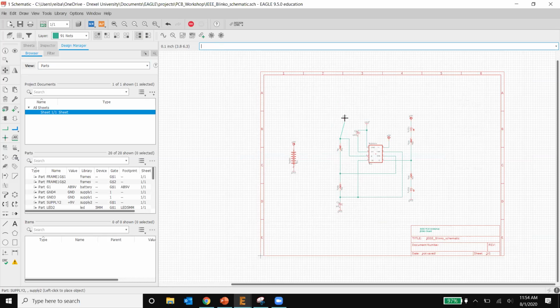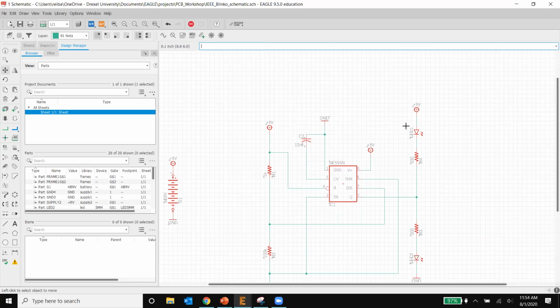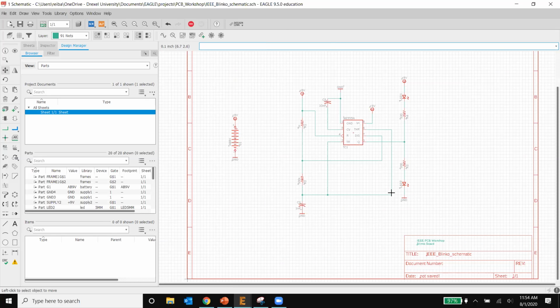And the good thing about moving components is that if they're netted, it's going to bring the line with them, which is nice, and it's not going to mess up, let's say, your whole board. Other advice that I would give for using this would be to use your cursor as much as you can.